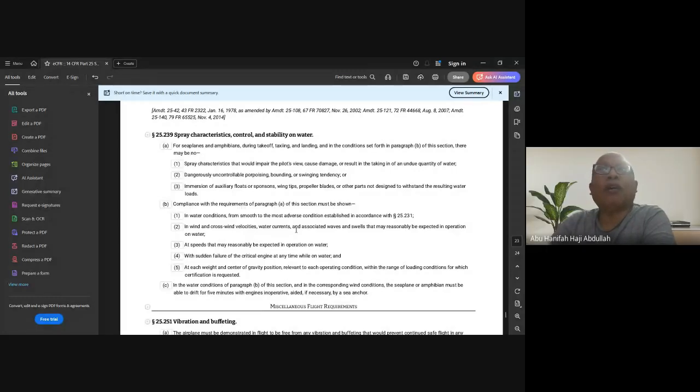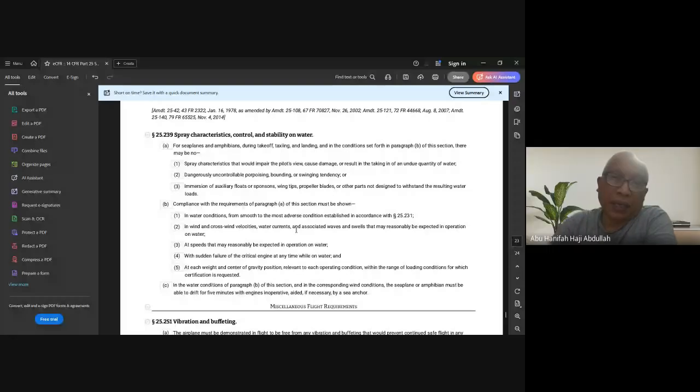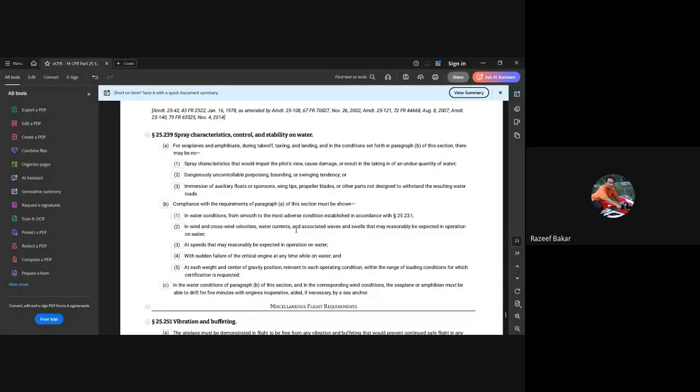However, you need to look at all these, 25.239, also longitudinal stability, static stability, empty weight. You have to go back through the whole Subpart B because the pontoon adds extra weight. Malaysia can adopt code from other authorities. Yes, Malaysia can adopt code validity, correct. If your DOA has the scope of approval, then okay. But I don't think we have that scope of approval now. Yes, we don't have it. So that is another issue.